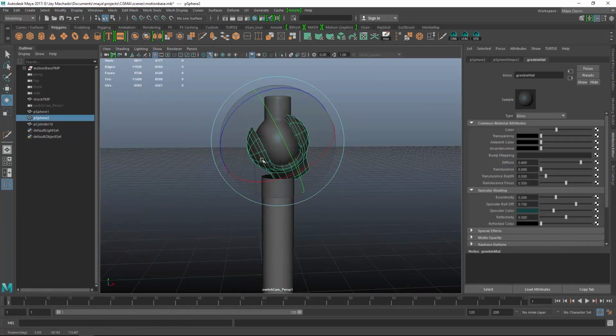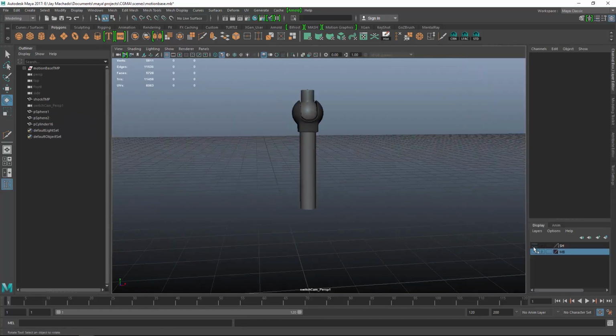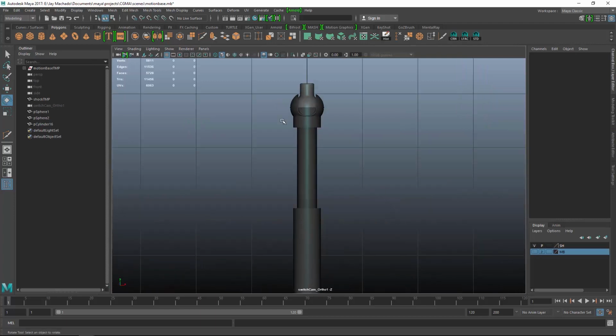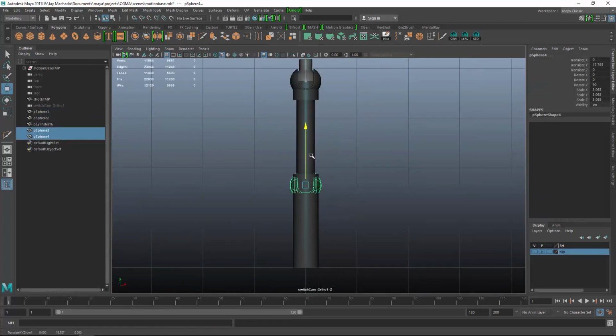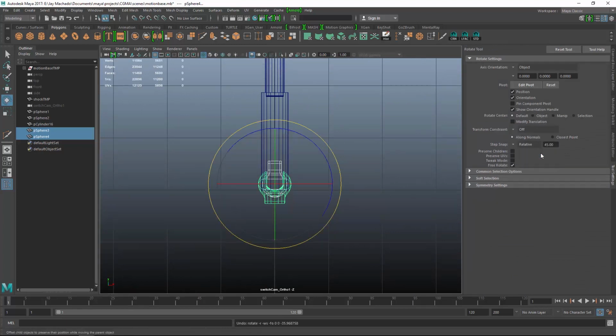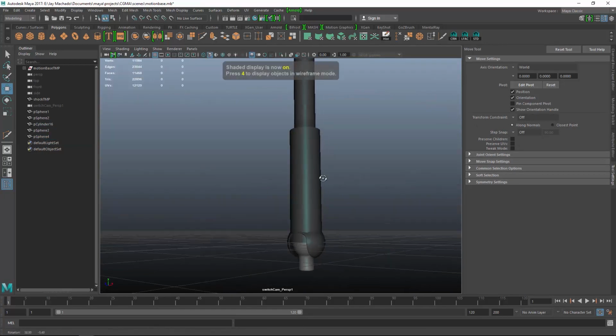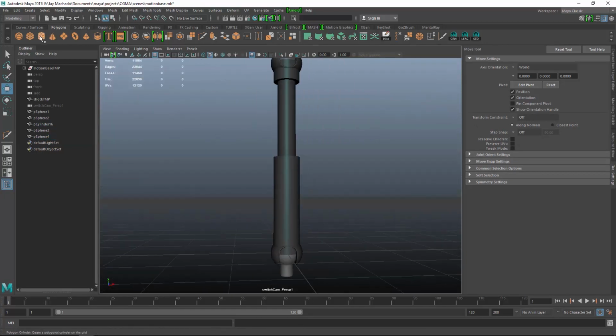So now we've got our socket shape, and we can kind of rotate it around the ball. And you can see it might crash through in certain places, but that's okay. So now for these, I'm going to duplicate them for the bottom of the shock. I'll set the step snap on my rotate tool so I can get a perfect 180 degrees easily. And I'll just go ahead and snap them down to the origin.